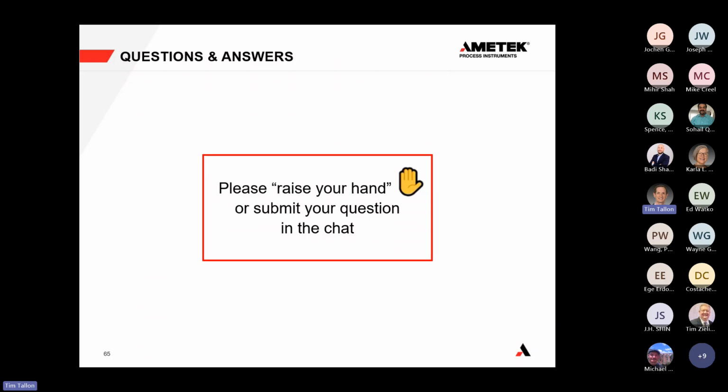So as far as any type of combustible, it's not so much that it depends. It's like as long as there's going to be incomplete combustion of carbon monoxide and hydrogen. So in most cases, yes. Let me answer this question a little bit more clearly. The combustible measurement will measure carbon monoxide and hydrogen and anything in that window. The hydrocarbons measurement is slightly different and a little bit more particular.